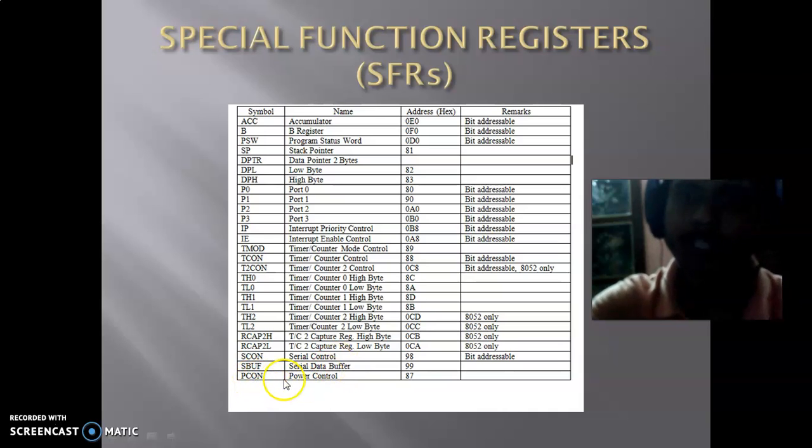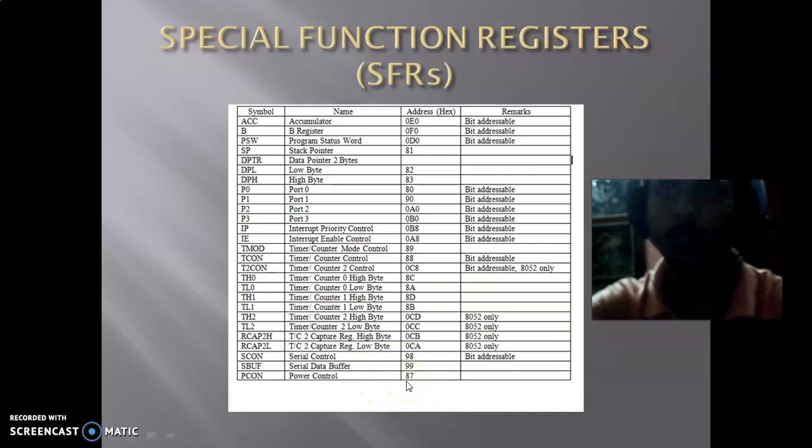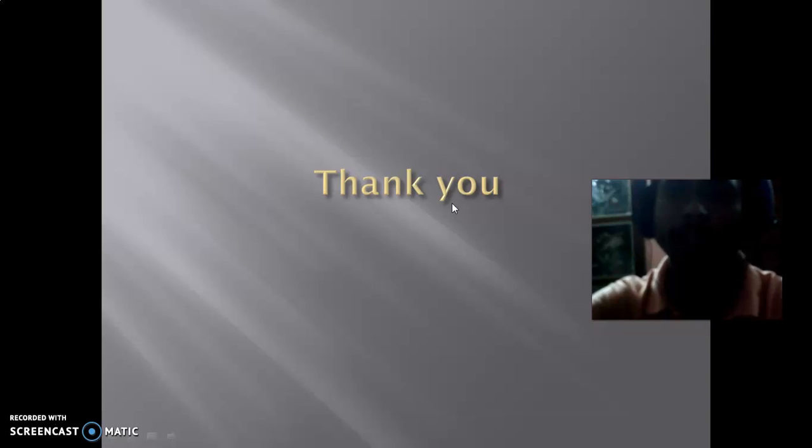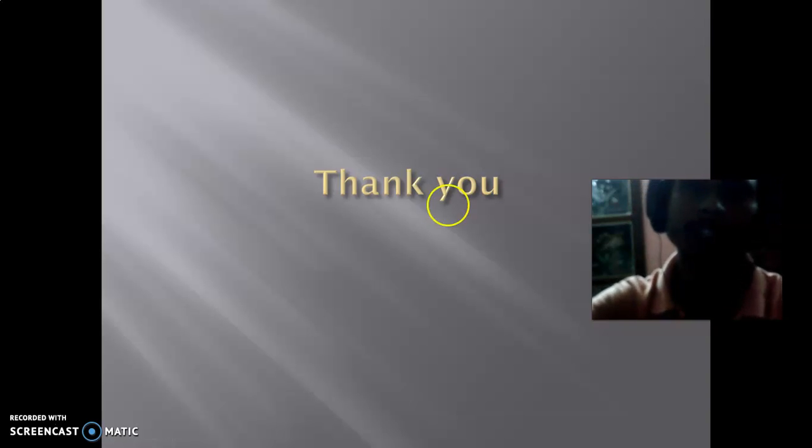So now the next one is the PCON register. This is a power control register. This is not a bit addressable register, and it is used as a special purpose register also. So that's all. I already discussed SFRs and RAM memory organization, and the PSW of the 8051 microcontroller.